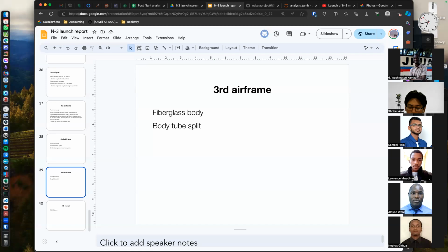Then equally, in terms of the design of the bulkhead, I saw you are putting in a bulkhead as a component. I would prefer that for the next airframe design, we make it a module whereby the whole system is completely sealed, so that the next compartment just has an attachment to this, but should not have a free attachment in the form of a bulkhead. The bulkhead should be an integral part of the lower casing.